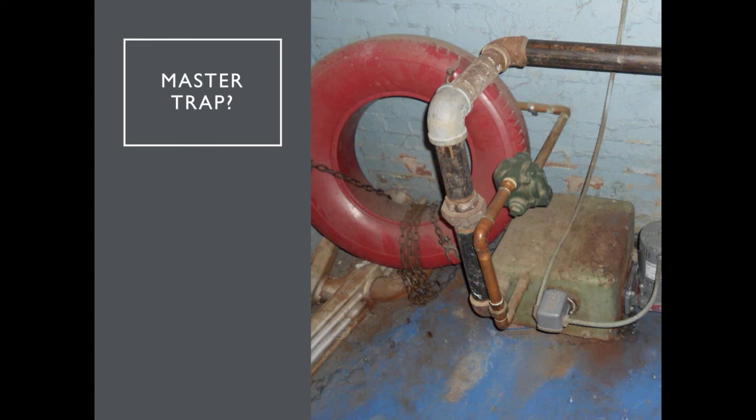And a question from Benjamin. He says, how do I remove/eliminate air? Oh, air from a steam system, that's a great question. On a commercial boiler, they will use a deaerator, which uses steam to heat the water and remove the oxygen. On a typical small commercial boiler, you'll need to talk to a water treatment company.